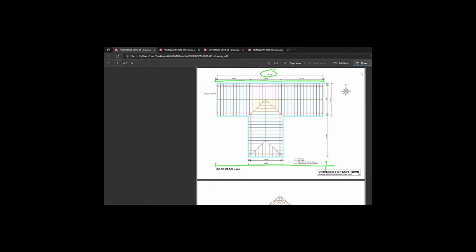And the 10.9, if we were to look on this face, at wall plates specifically, these individual lines indicate trusses, but we do not have any trusses resting on these exposed brick areas. That's because that's a parapet wall on those gable ends, and there are no trusses that rest on the gable ends. So the 10.9 does not extend that full length, and you'll find it there. 10.9, 26.5, 26.5 there, and 10.9 on this side.